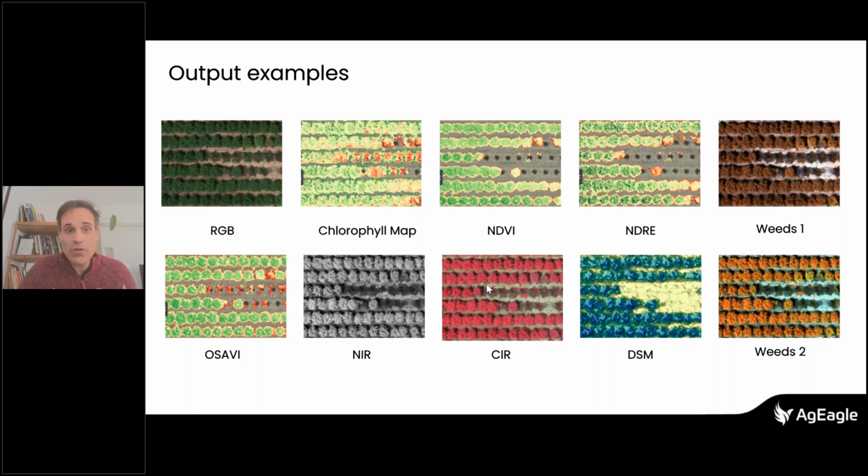So what I would mostly tell you is you can get like 4 products: the RGB image, which is good for visual interpretation; the NDVI, which talks about the size of the plant and the amount of leaves; the NDRE and everything related to NDRE, which is the chlorophyll content of a plant. So that will be 3, and the 4th is the DSM.